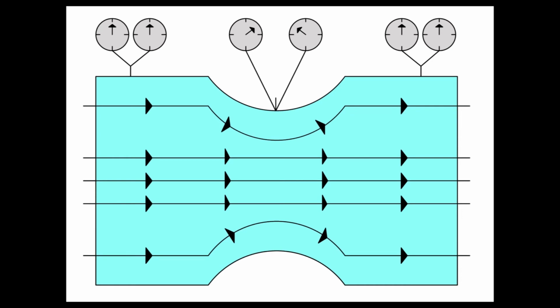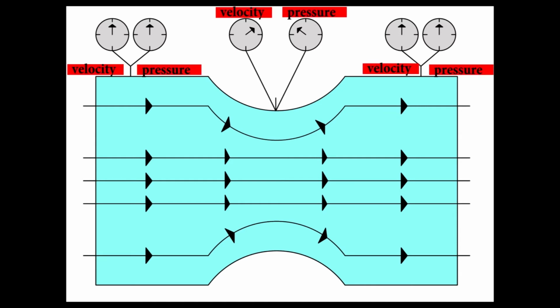Bernoulli's principle is explained practically by a Venturi tube, which shows movement of air and how velocity and pressure change. Inside the Venturi is a constriction in the middle, and pressure and velocity are checked. In the beginning, as air is passed through the tube, the velocity and pressure are equal.